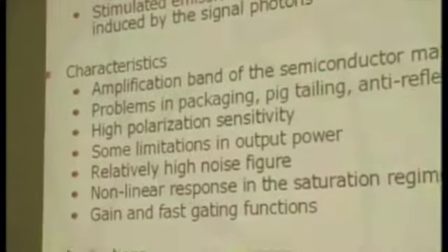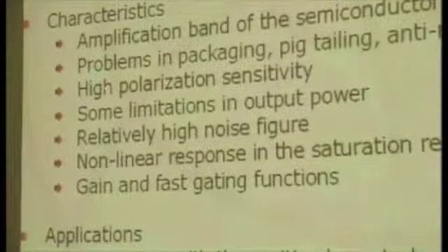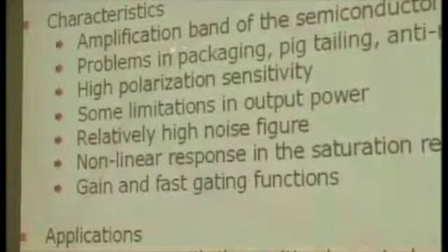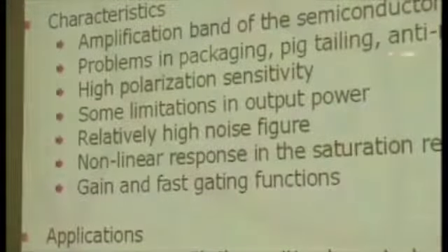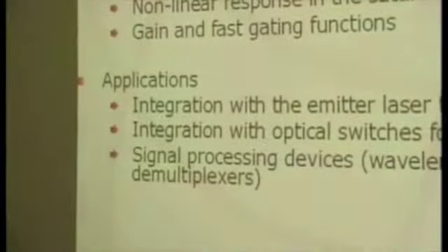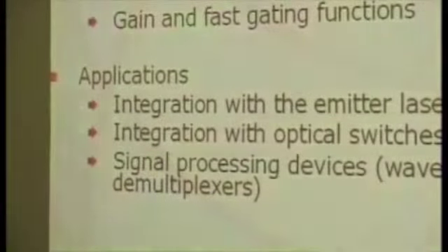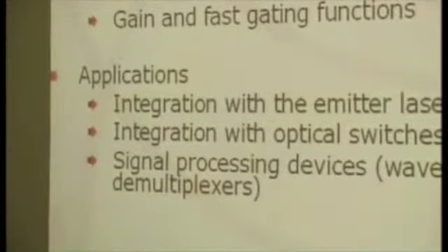And this is just the same as a semiconductor laser. The amplification band is the same as the semiconductor material. The problems are in packaging or pigtailing, anti-reflection coating, high polarization sensitivity, which means it depends on the polarization state, and some limitations in output power.